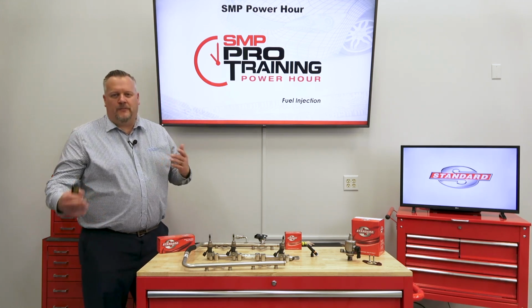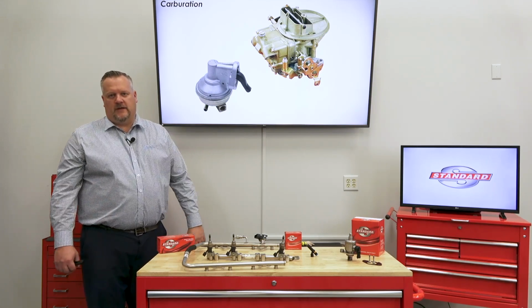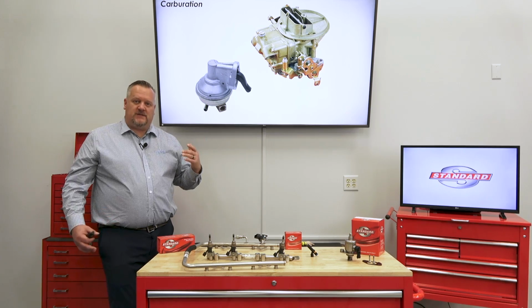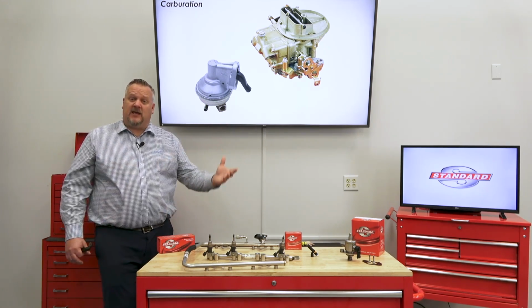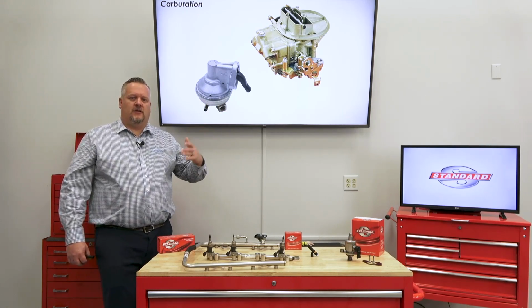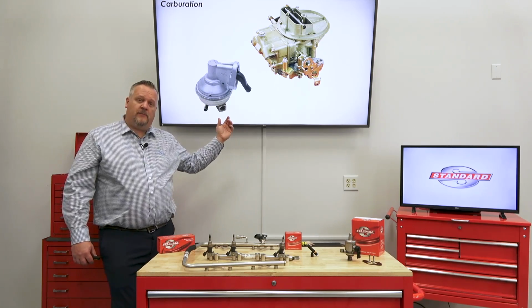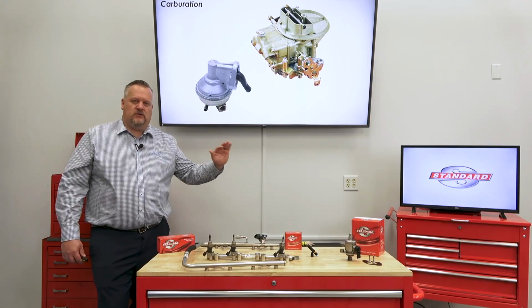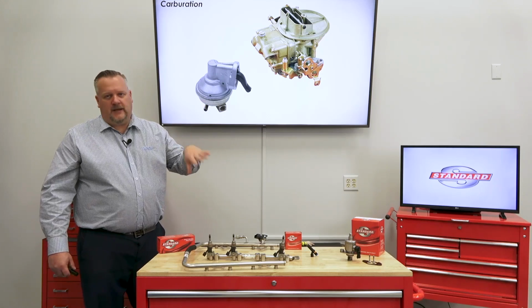All right, so let's jump into the presentation here and just do a quick review of fuel systems throughout the years. So first we had carburation. Now this is a very minimally controlled fuel system. It was kind of preset. It was based on some different jetting and internals of the carburetor and the amount of vacuum being drawn in the system in order to deliver what was an estimated amount of fuel. And so we had a mechanical fuel pump drawing fuel from the tank and then sending it at low pressure, typically about 2 psi, to the actual carburetor itself to dump it into the engine.